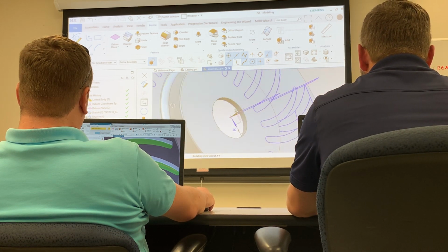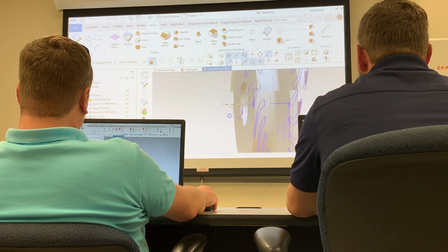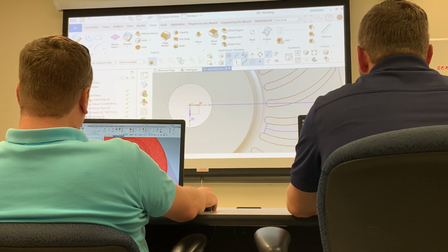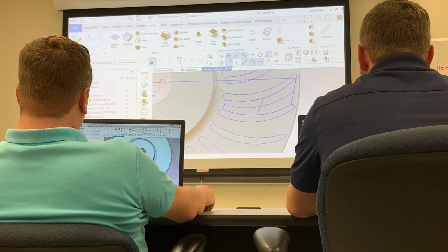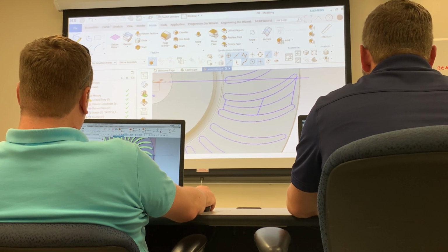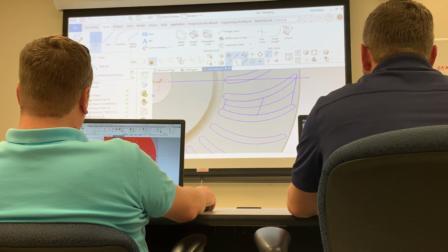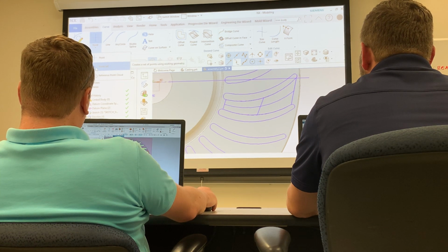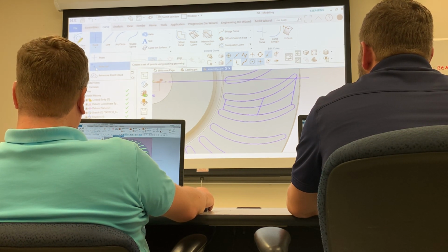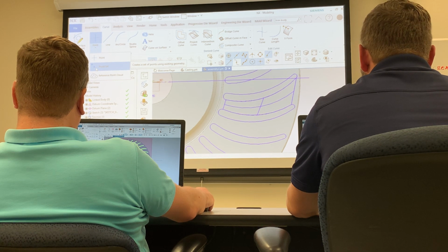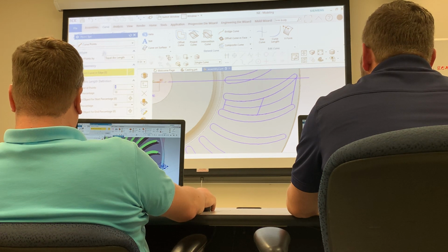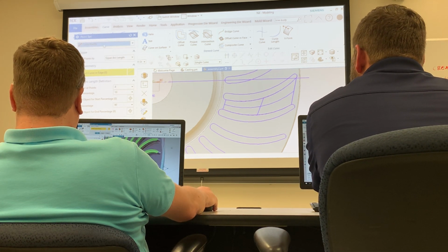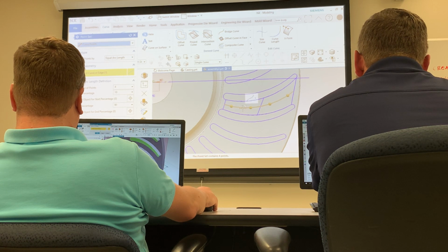And you might think, well, why didn't you go ahead and just put the points in there? Just because I want to show you this one neat little thing. We're going to have a group of holes lying on here. You go to curve and then go to point. There's a thing called a point set. I just wanted to show you one way to use this thing. Pretty nice. So under the curve tab, point set, and just search for point set. And we want curve points, and we're going to select that curve.